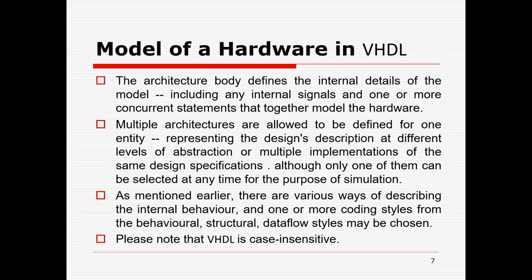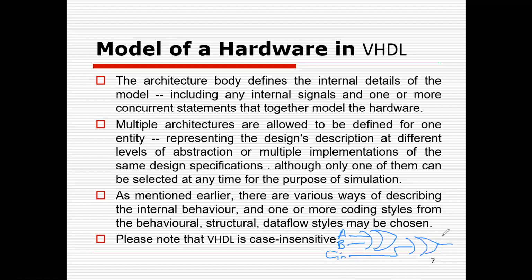Now, hardware is not something which works sequentially. If you have, for example, a 1-bit full adder, you will recall you have an XOR gate followed by another XOR gate. And then you have, maybe I'll draw it, I'll use a notation and draw somewhere. This is your A, B, and this is carry in, and this is your sum. And similarly, you have A, B, and there is one more, I should have done it, but I have less space over here, and then an OR gate.